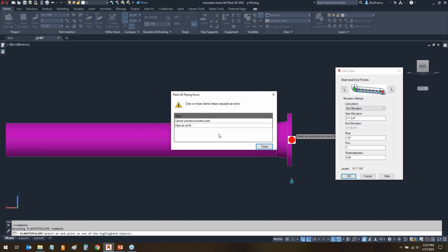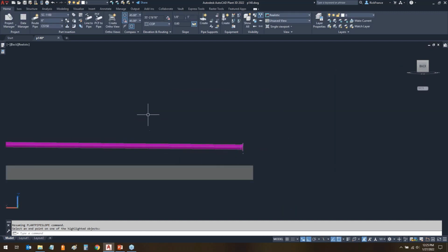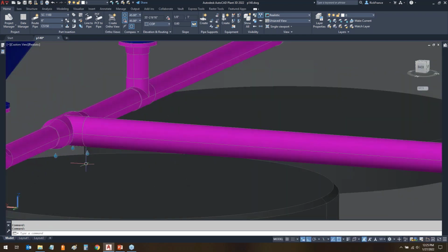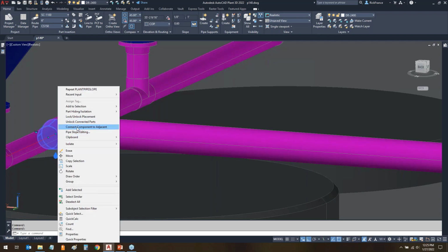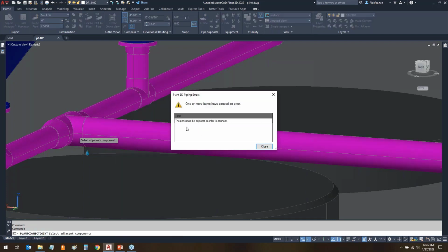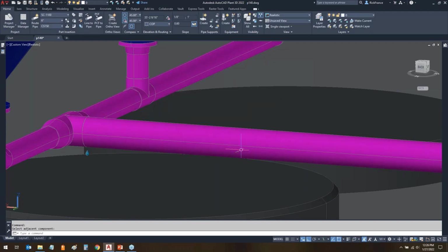As soon as I hit yes here, it tells me now the parts don't fit. Hit close. It tried to slope the pipe, but if I come up here to the T, you can see I now have leaks, 3 of them, because it broke that T from the 2 reducers and from the pipe. Now I could easily, since the T didn't actually move, connect the reducers back up to the T. That solves that problem. But it will not let me connect the pipe back to the T because they don't connect anymore. It's broken. That's why I can't include a T.